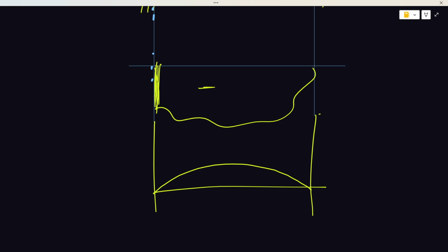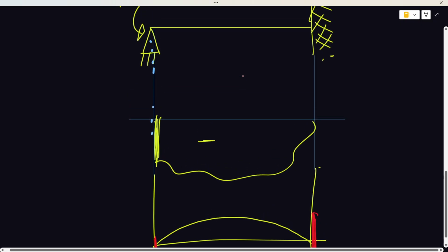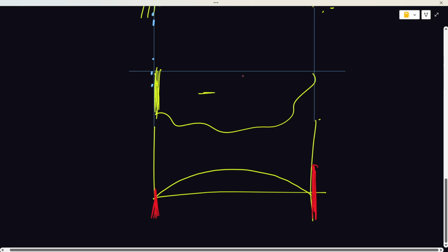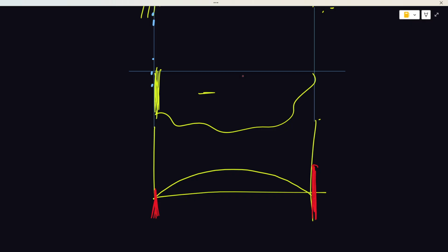Do you get? But now, remember that at this side we have a fixed end, and at this side we have a hinge end. So remember, a condition for a fixed end is that there's no slope. So we need to adjust the elastic curve diagram to make it aligned with that condition. To show that there's no slope, we have to redraw the elastic curve and put it that there's no slope. Something like this.